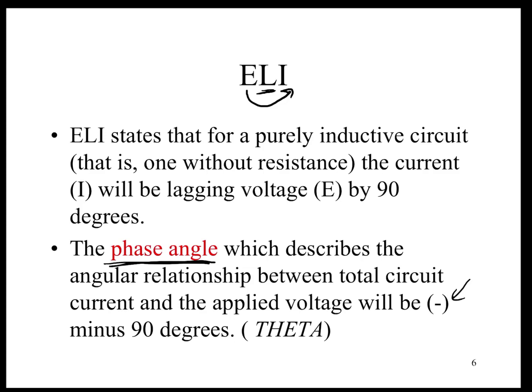In reality, circuit phase angles aren't usually assigned a polarity of plus or minus, but it is important that when you consider the phase angle of any circuit, that you express some way or another whether it's the result of current lagging voltage or current leading voltage, whereby the type of reactance that's providing the load can be identified.